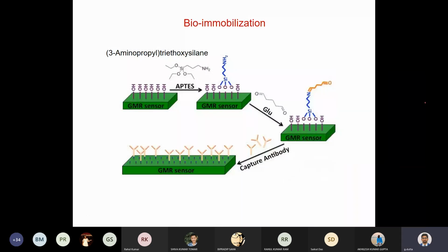Okay. So this makes the sensor surface hydrophilic. First, use acetone and sonicate it for 10 minutes in a beaker. In a beaker, just take all your sensors, dip them fully in acetone, and sonicate for 10 minutes. So the organic contaminants can be removed.